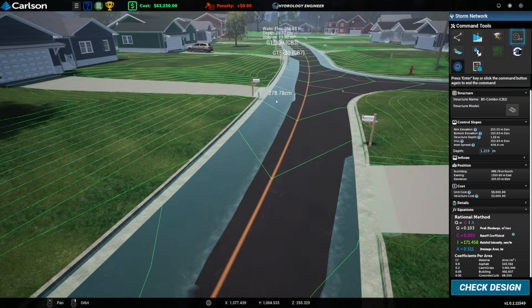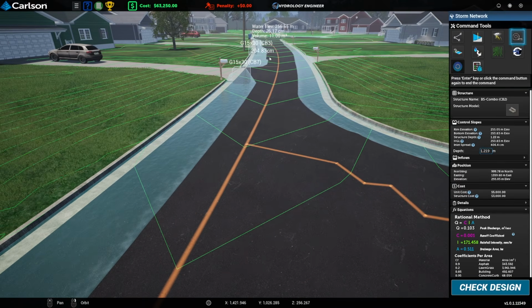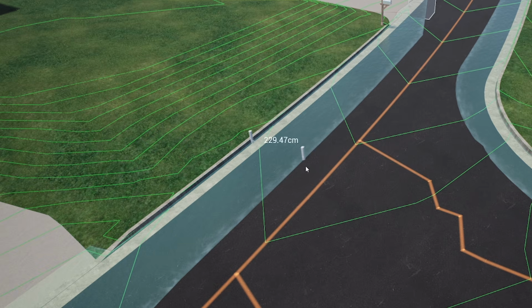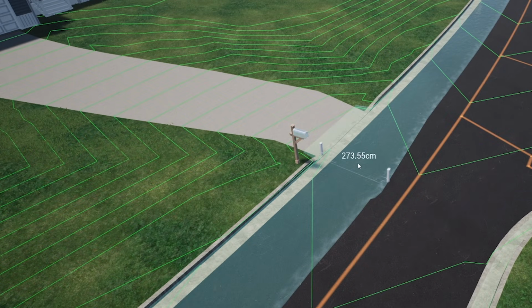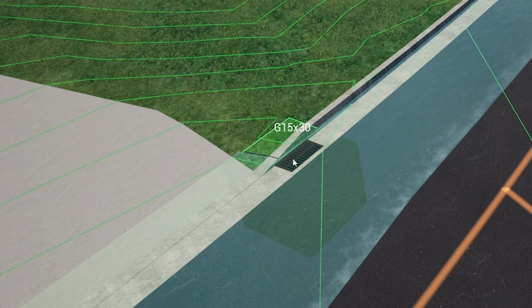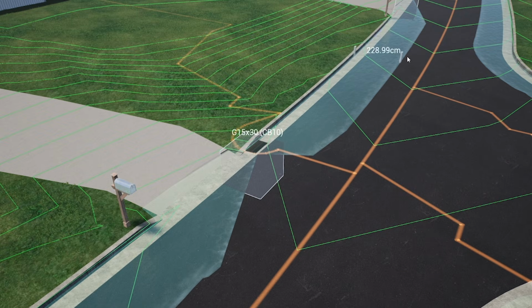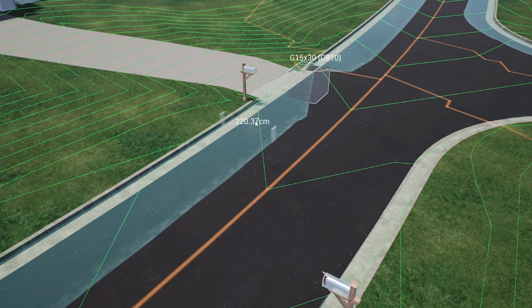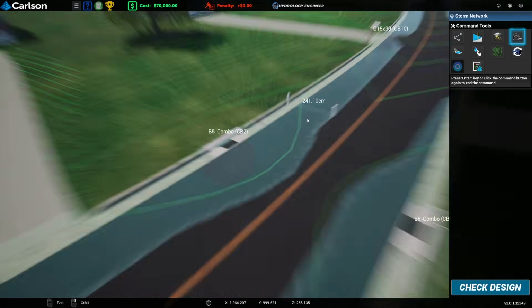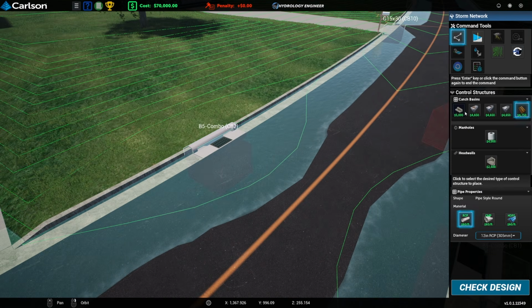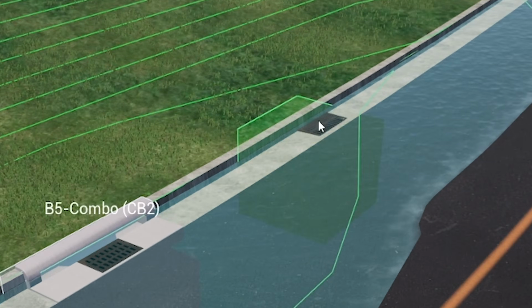I think that's mostly because we haven't finished doing our drainage up here. So we put that gully in last time. We go find where 2.4 is. Is it going to happen? It's going to happen at a driveway again. So put another gully there. Run the storm again to see how that worked. So yeah, that stretch is all below 2.4. Then down here, you can see it gets to 2.4 before we get to our combo gully at the bottom. So let's shove that in there.